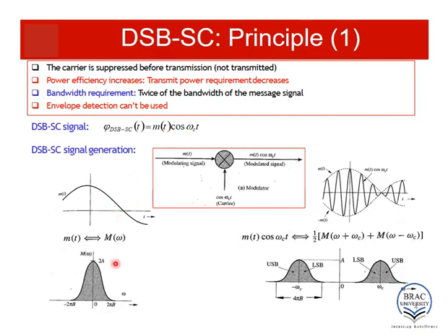Let's assume this is the frequency spectrum of this time domain signal. When we are modulating this signal, the equation is m(t) cos omega_c t. As you can remember from the Fourier transform, when a signal is modulated with a cosine carrier, the spectrum of the signal is shifted to positive and negative values of the carrier frequency.